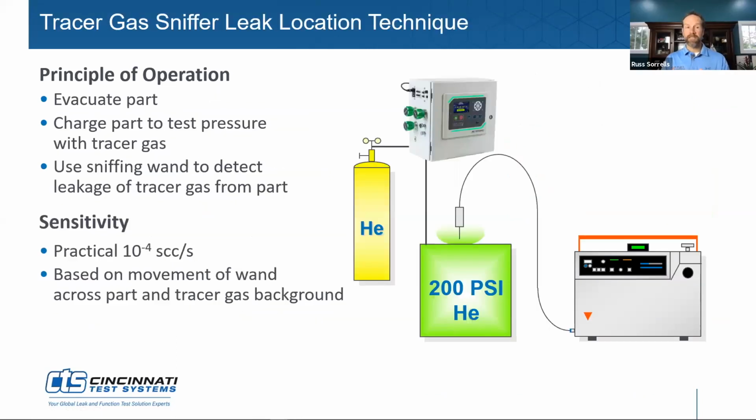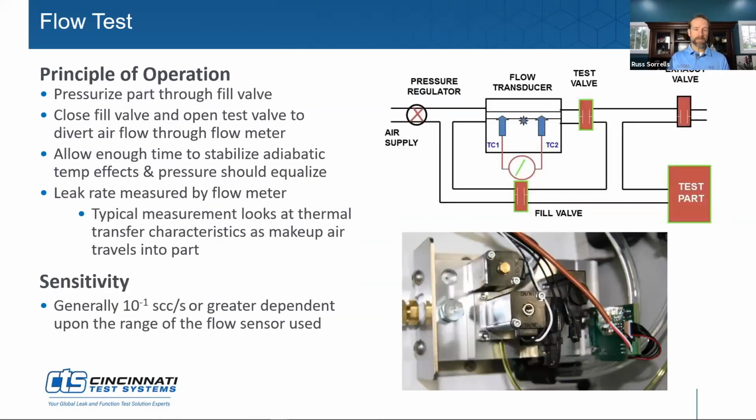And so the challenge in choosing which flow meter to use is you say, well, gosh, I'm measuring a 5 SCCM flow rate. I want to use one that's 0 to 10. But the problem is if it leaks 15, you also want to know that it leaked 15, and that's outside the range of the flow meter. So that's some of the give and take that we have to make when deciding which flow meter to use in the application.